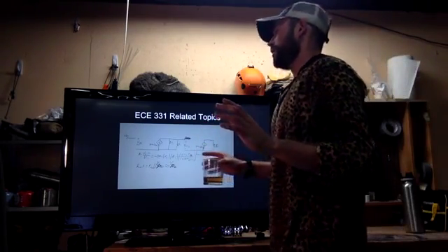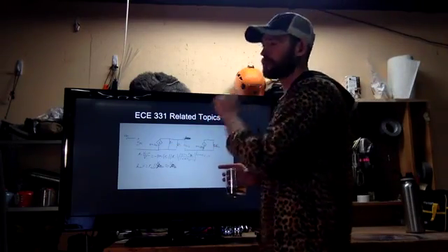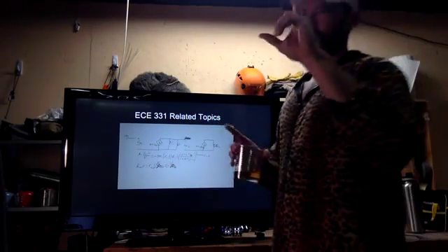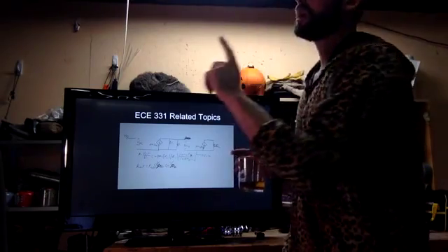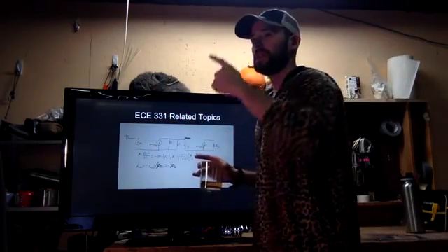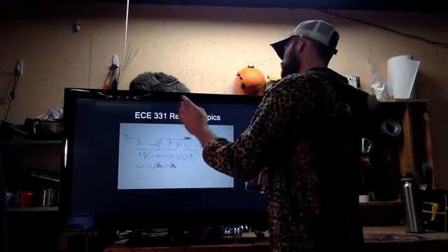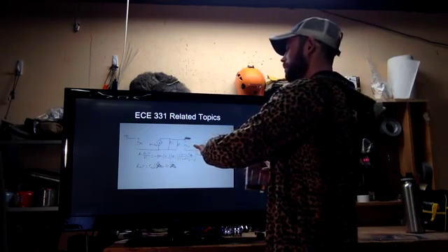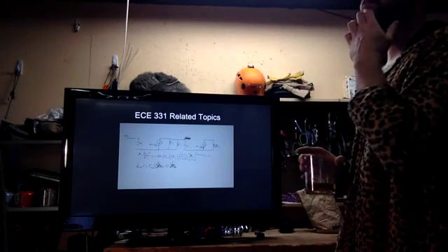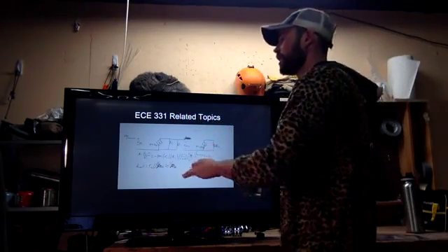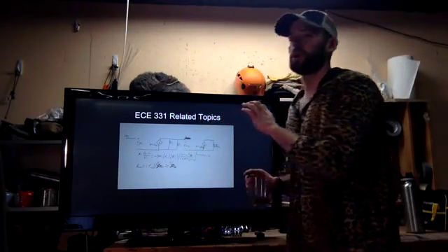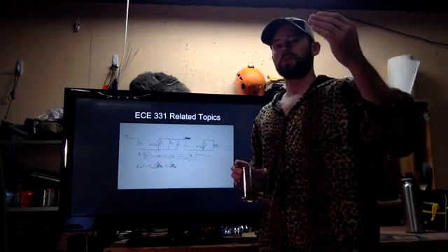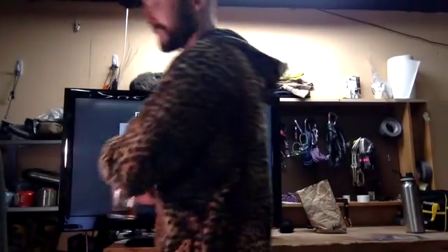And so the gain ends up being the negative transconductance of the first transistor times the resistor in parallel with R1, which was a resistor in the actual circuit, which is multiplied by the resistance of the second resistor. So from a 331 aspect, it's much easier to analyze these circuits from a small signal model, which is what this is.